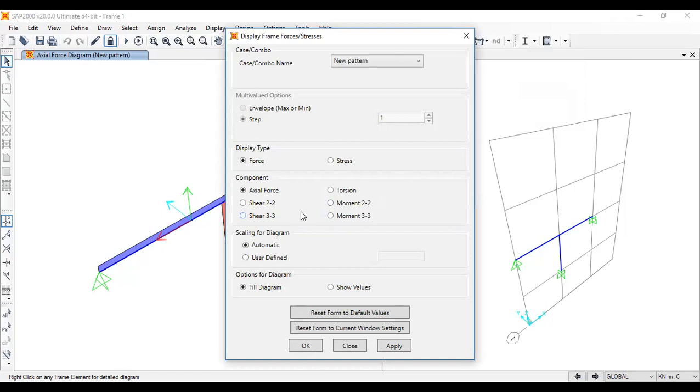So you can read the documentation and solve, right? That's important because these are fundamental concepts you need to know, right? It's local axis system and global axis system. Because in joints, you show the results in global xy, right? But for elements, it's in local coordinates, right? So it's always in the local coordinate system. For joints, it's global coordinates. Global xy, it will give the reaction.